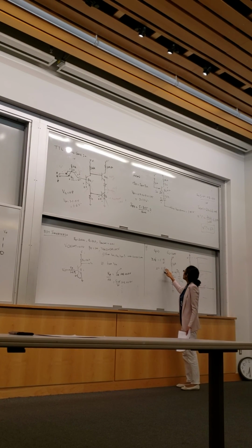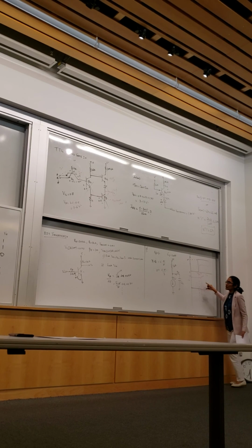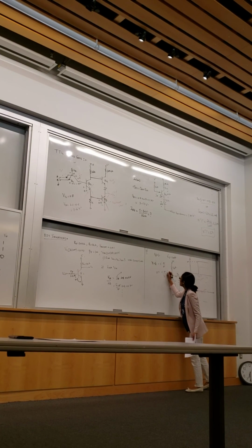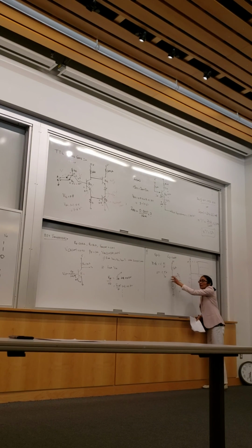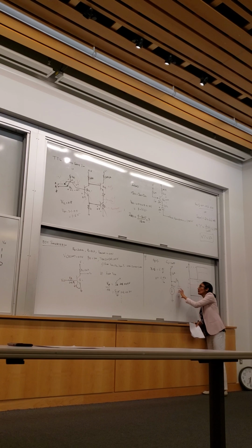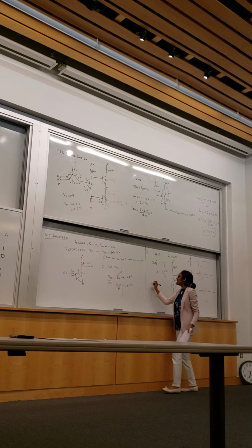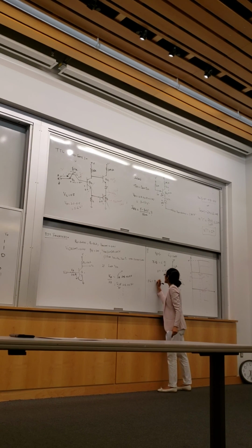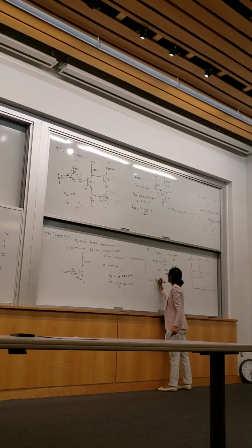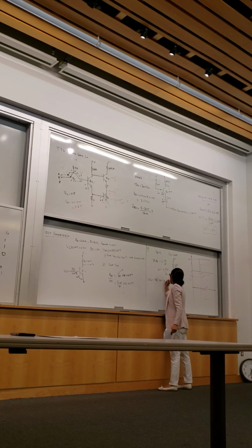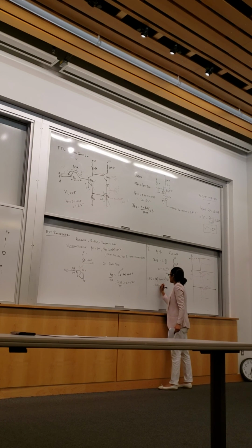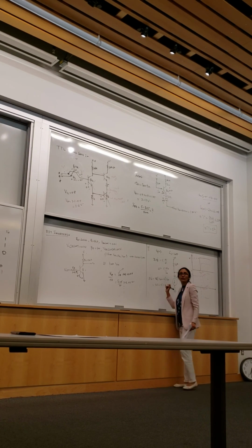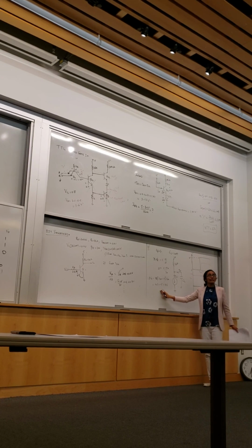Now the output voltage. If you look at this formula, this is delta V naught and this is I naught. That's what's changing the voltage in the load capacitance, the voltage change and the current change. The voltage change is easy. What's the voltage change? That's 90% of VOH minus 10% of VOH. That's 4.5 minus 0.5, which gives you 4 volts. You see what I did? Your VOH